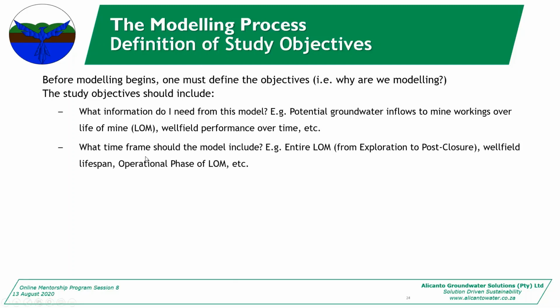Okay, other consideration, what time frame should the model include? Is it for the entire life of mine? Is it from exploration to post-closure? Is it for the lifespan of my well field, which could be 15 to 20 years? Operational phase only, where you're excluding closure and post-closure? How long does my model need to run for? Is it a flow model, transport model, or is it a combination of both?